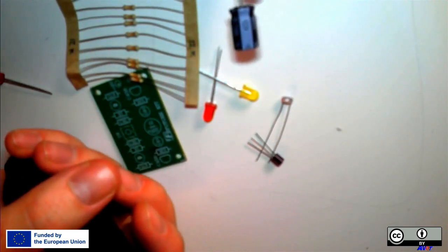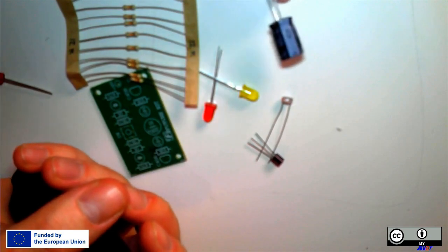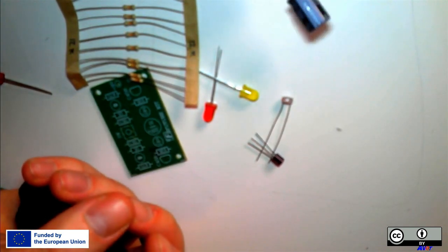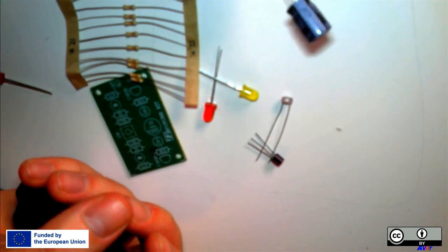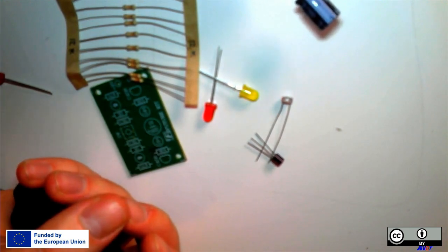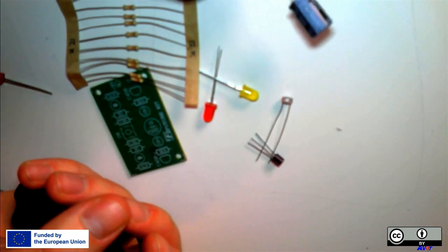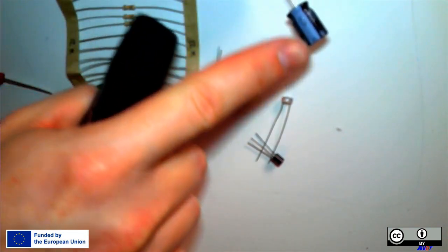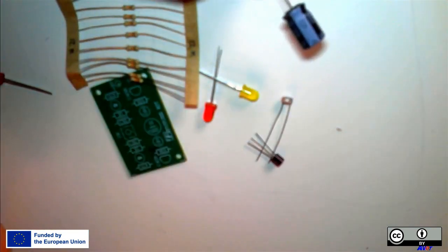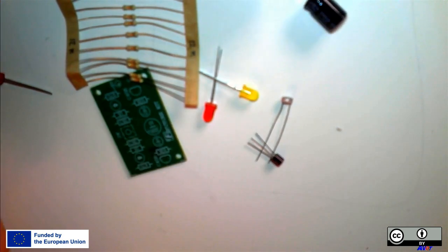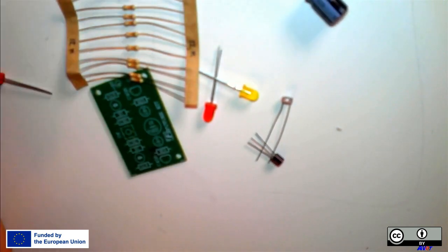This one is polar, meaning it has a negative and a positive side. Some of them work both ways. This one works one direction, and you can see the line here with the white would normally indicate the negative side. These are very useful to create oscillating circuits. That could be an astable multivibrator, or we use them to maybe protect parts that cannot have a large change in flow. So sometimes we use these to make a more steady flow of electrons in the circuit.